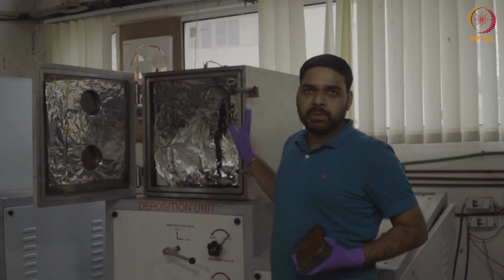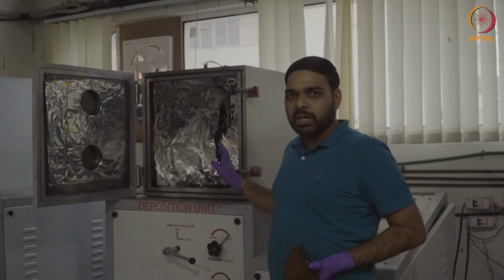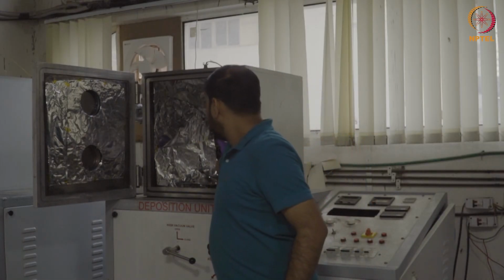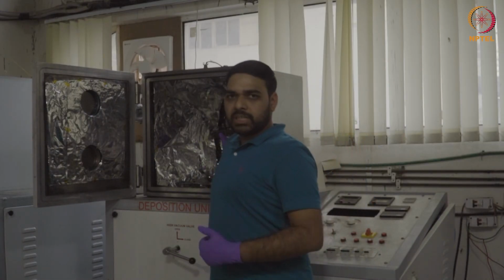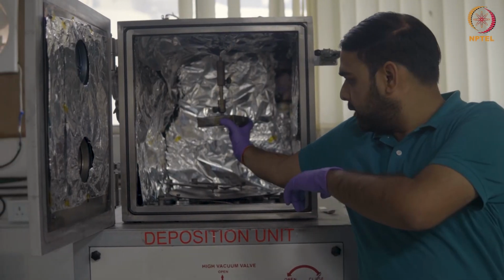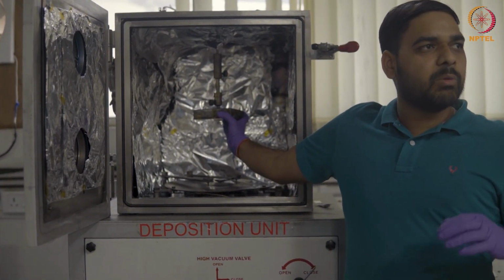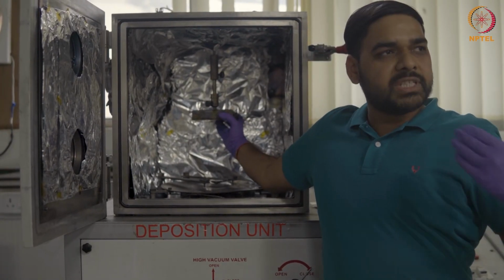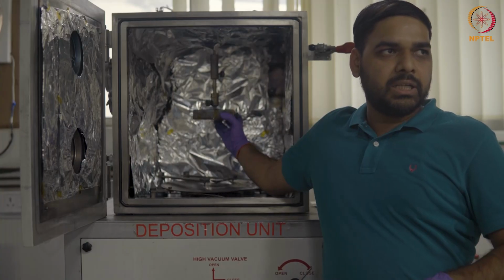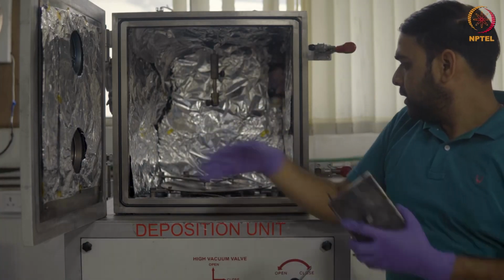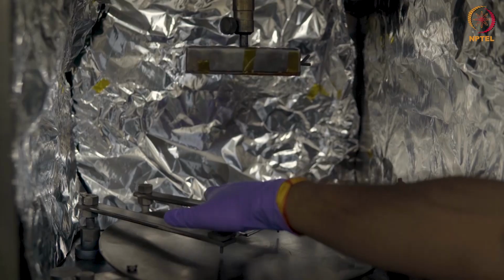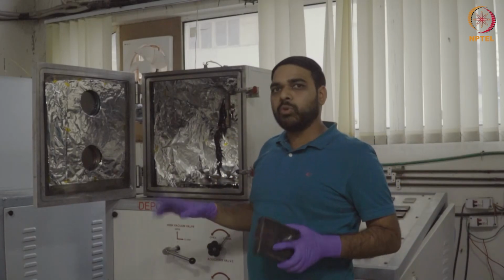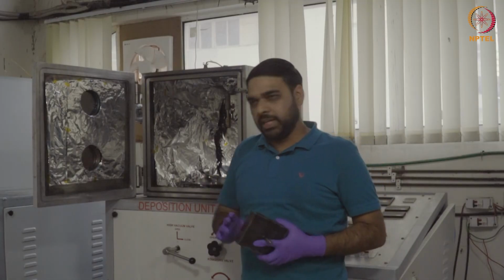So this is the basic chamber inside of the thermal evaporation unit. We will be putting our substrate material here on the top, and at the bottom, in the tungsten boat, we will be putting our source material, which is nickel titanium, let's say, for the current case. This tungsten boat is being heated with the help of two copper electrodes, which are supplied very high power up to being red hot, which melts and evaporates the material.